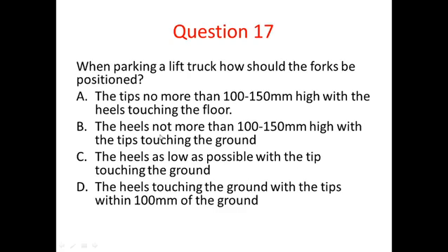When parking a lift truck, how would you position the forks? Well, you'd want to make sure that the forks are in a safe position, i.e. the tips are on the ground and the heels are as low as possible. This produces the smallest trip hazard possible. So tips on the ground, heels as low as possible. We've got this one here to see.